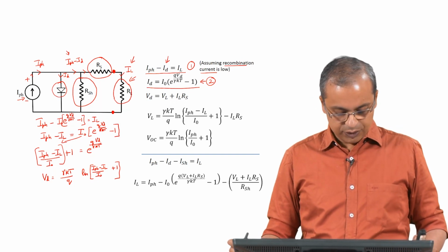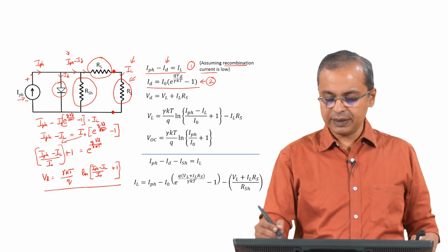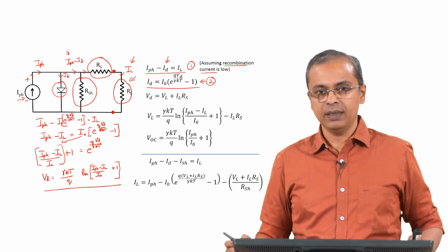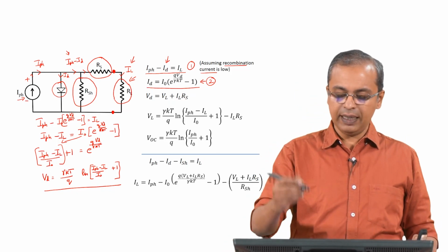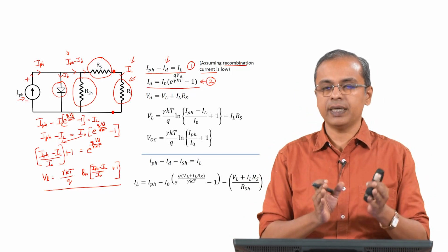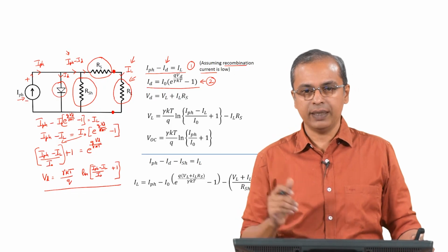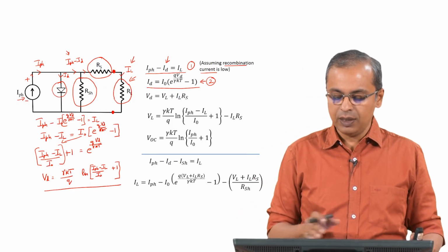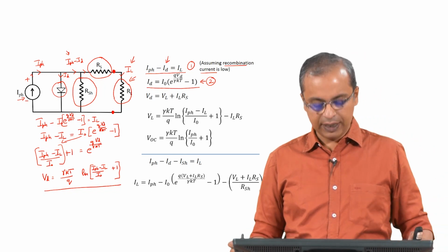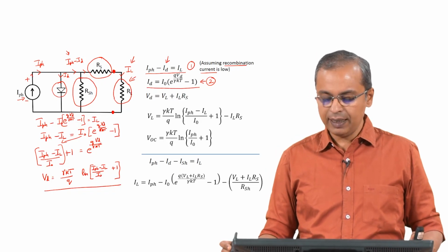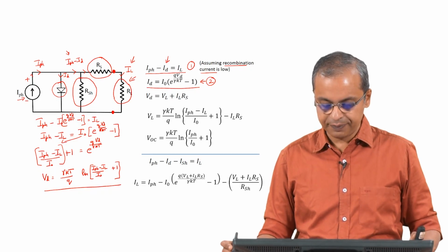So, that is the other equation that we have arrived at simply by substituting equation 2 in equation 1. Equation 2 is the expression for how the diode current varies as a function of diode voltage, and equation 1 talks of how the current is distributing as it comes off the solar cell into either the load circuit or into the diode that is internally present within the circuit. Now we only have the load current, the photo current and I naught, and with respect to that we have an expression for Vd. So, this is what we have put together.